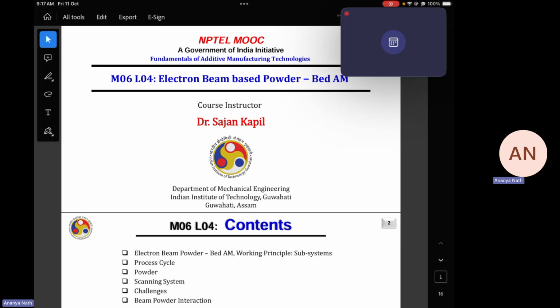So this is the concept of DED, and in LPBF recoater design is very important, because the recoater is the instrument actually responsible for good quality. Other process parameters are also there, but the recoater has a very important role in PBF, powder bed fusion. Over the build plate the powder is spread and the powder bed is made, so the spreading is very important.